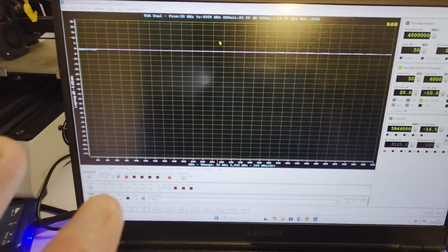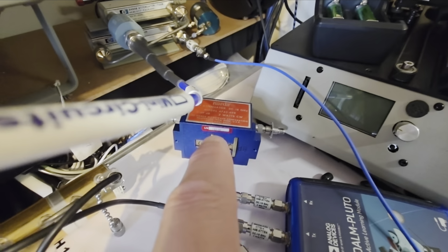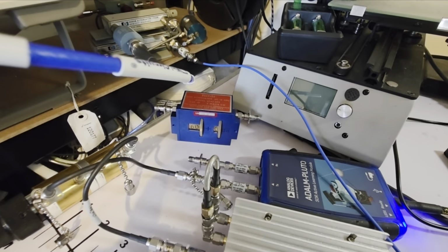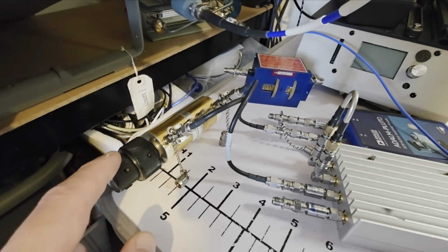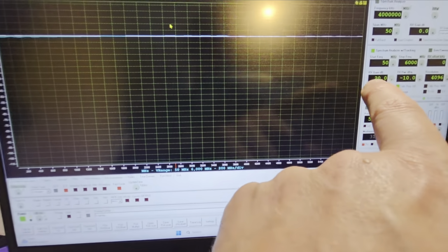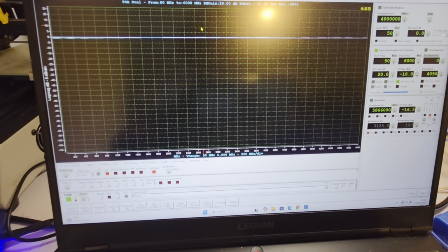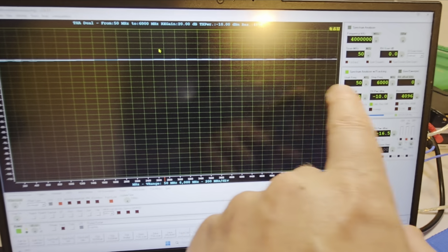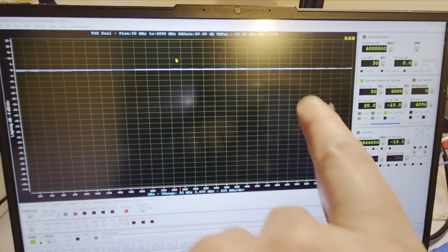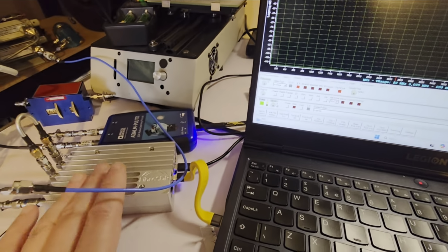So we're going to test the dynamic range because I have an attenuator of 70. Well, I have another there, very nice as well, but I'm going to use this one. So I know that I won't have 70 decibels at least at 6 gigahertz probably, but over 50 is crazy. If I can get a good linearity in attenuation, even if some fluctuation appears, it's crazy for what you pay for this.